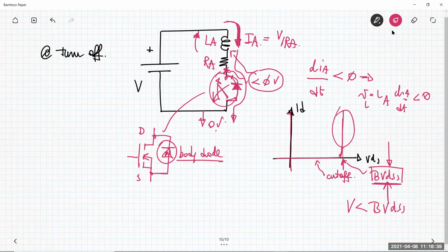If you are able to operate the MOSFET at the breakdown voltage without involving too much energy, that situation can be affordable. Because if the energy is not so high, the semiconductor material does not have the time to increase the temperature over the maximum temperature admissible for that specific semiconductor, which is about 150 degrees, 170 degrees.